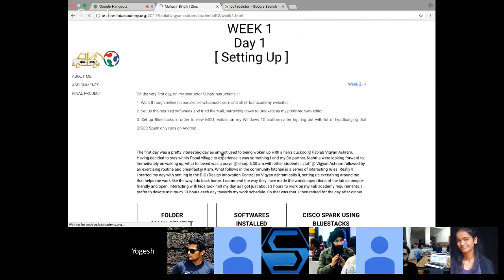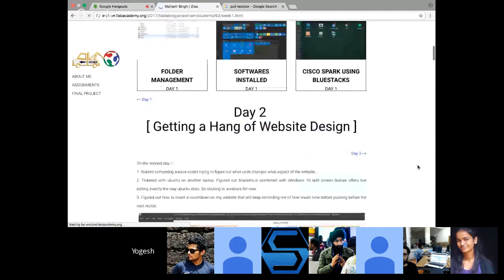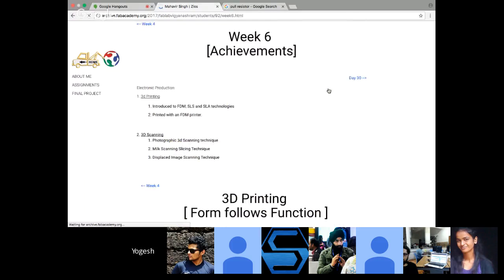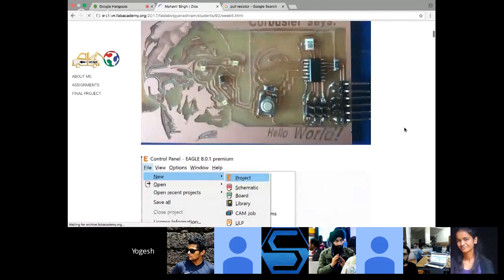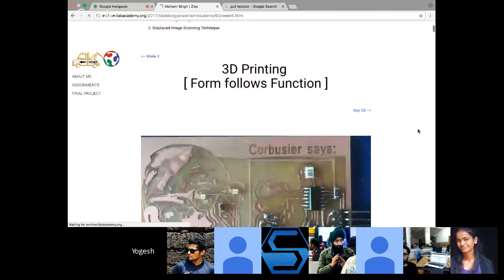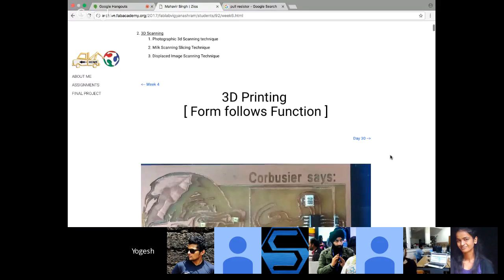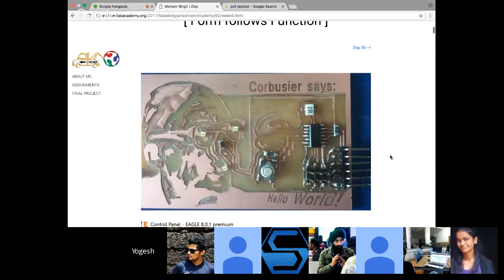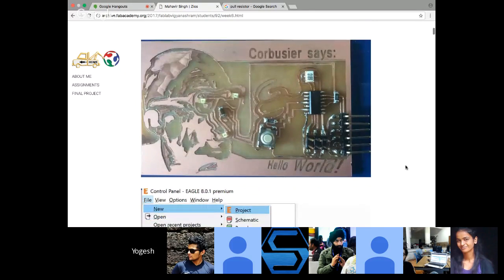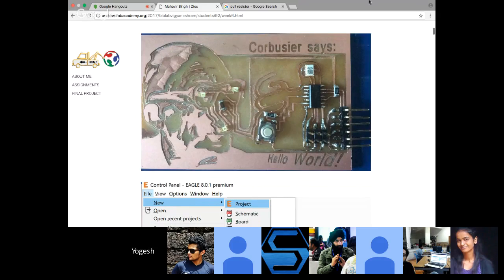So week 6. I haven't updated the website too much. I just put in the images to show what I achieved. Basically, this is a 3-tier PCB fabrication. For example, let's say I have a trace file, a cut file, and a shiny file as well. The shiny file is basically the PCB cutting at 0.02 mm, which gives the copper a nice shiny finish.